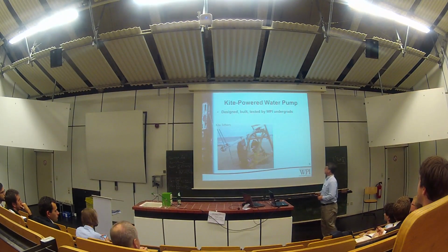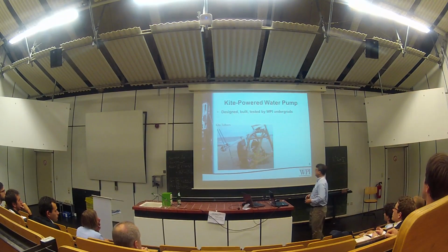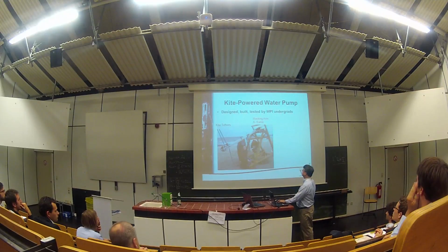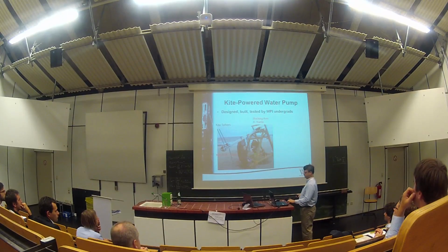So here is the system then, and I'll talk you through it a little bit. It's not a pumping system, it's a bit different. It is based on a rocking arm. So here's a rocking arm with a pivot and an A-frame. The kite aerodynamic angle of attack control is down here. We'll talk about the details of how it works later, but these are just drawn in. We do have two kite tethers, one to the leading edge, the power line, so to speak, and one to the trailing edge, the AOA control.